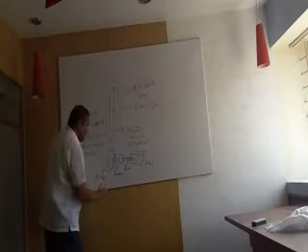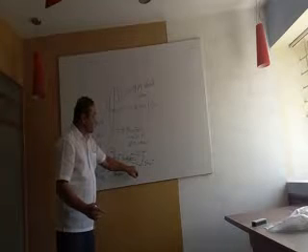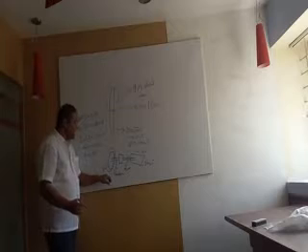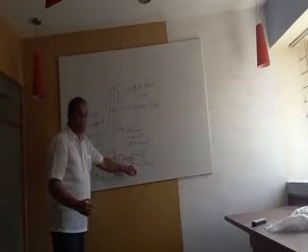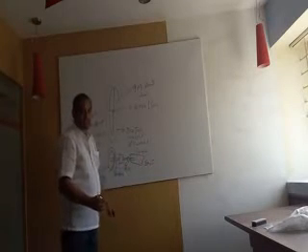The flywheel is rotated at 1500 RPM and the generator at 60 RPM. So the torque generated by the 800 ton flywheel is reduced to 60 RPM, and thereby the 40 megawatt generator starts generating electricity.